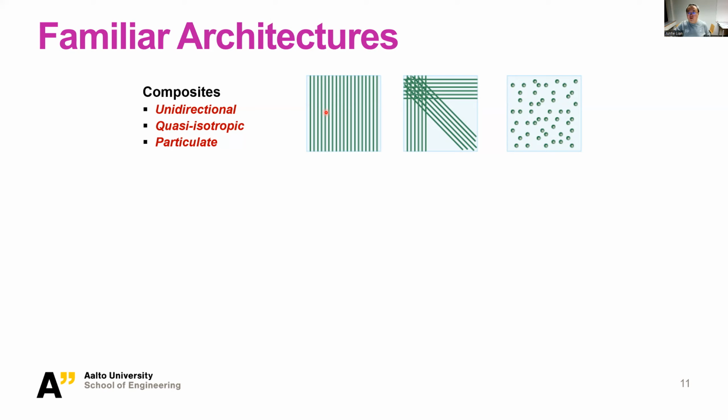the configuration. And already something more exciting is the so-called quasi-isotropic. So you have, let's say, three directions. In this case, when you pull it vertically and horizontally, your material will behave similarly. But if you pull it at a different angle, rather than horizontal or vertical, the material will behave, again, anisotropic. But this is another kind of configuration.